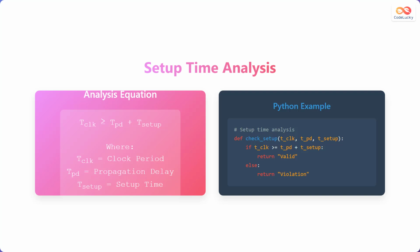Now let's delve into setup time analysis. The equation to analyze setup time is T clock must be greater than or equal to T propagation delay plus T setup, where T clock is the clock period, T propagation delay is the propagation delay, and T setup is the setup time. Here is a simple Python code that checks for setup time violations.